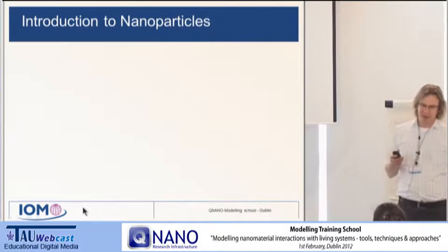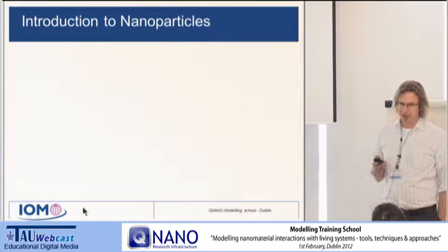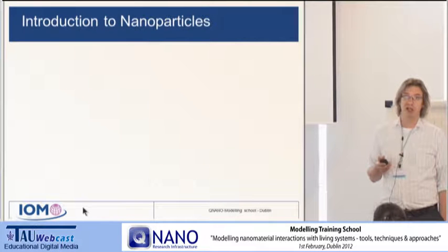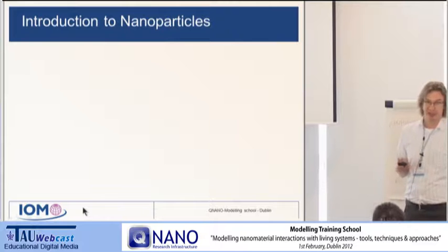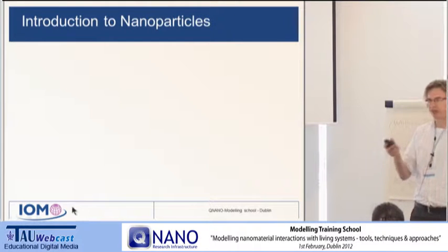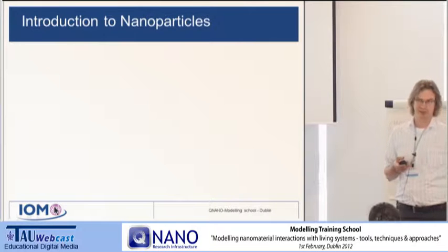Well, I think issues with coagulation you probably need to start taking into account when you're dealing with particles that are defined as nanoparticles, so 100 nanometers or less. I think there are some criteria, and it's a criterion of concentration also. But above that you probably don't need to take that into account that much.